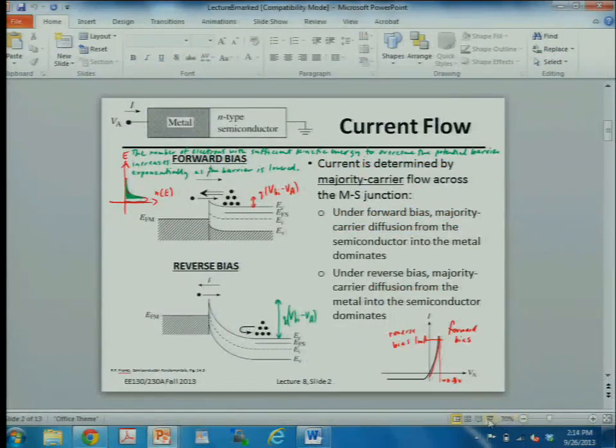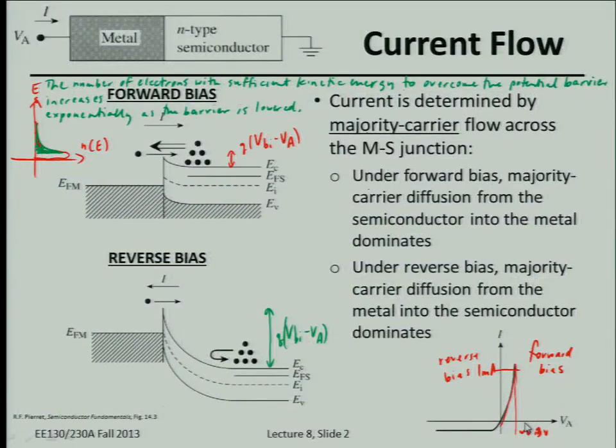So one thing that I'm not sure about: in the homework that was just due, or the homework that's due next week, we're going to be asking you to draw band diagrams, or you already did draw band diagrams this time. But it's implied, and I forgot to point out explicitly, that when you're applying a voltage across a junction, in equilibrium, the Fermi level is constant, right? The Fermi energy is at the same level in the metal and the semiconductor in equilibrium, so that there's no net flow of electrons, left or right from one material to the other.